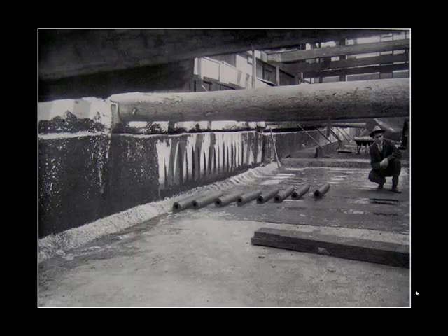The waterproofing is many, many layers of rolled out material overlapping, and that will then be covered with a protection course of either brick or concrete or some combination of the two. In the background, it looks like they're covering it with a concrete slab, but going up the walls, traditionally they would cover it with brick. This photo is about 100 years old, and my guess is this tunnel still has no leaks.